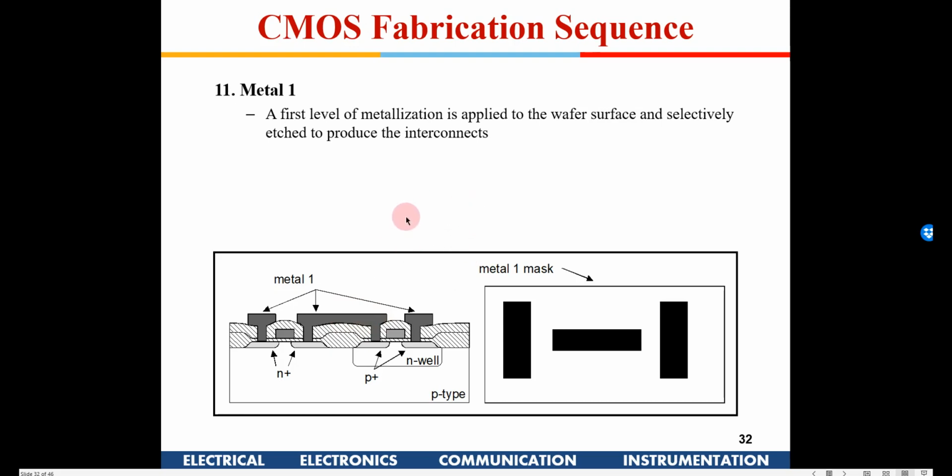Okay. So for a small circuit, manually if we give a preference to one particular metal, it is fine, but with millions of transistors, it will be very difficult. The software will run an algorithm and try to make whatever is best possible. The target is not to use one particular metal. The target is to reduce the overall chip area.